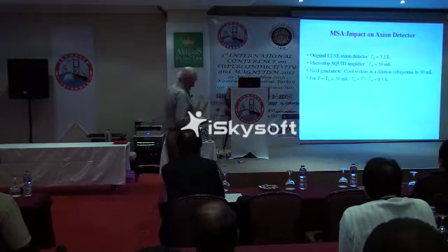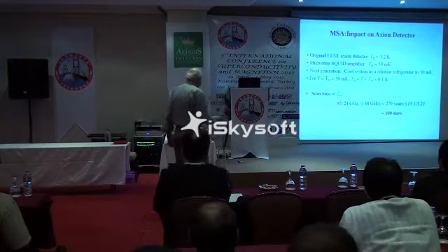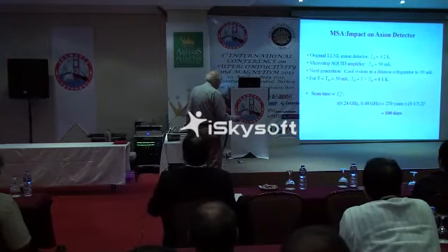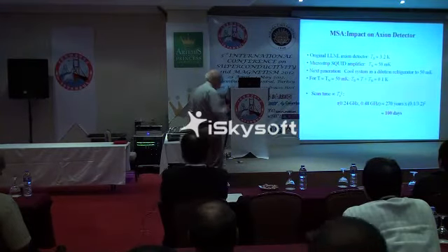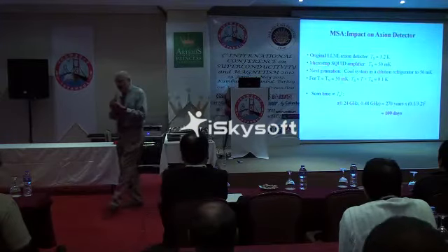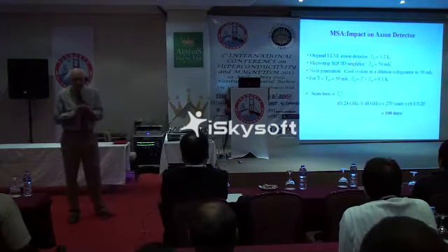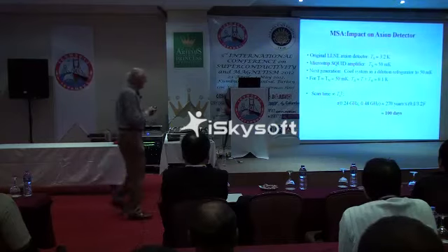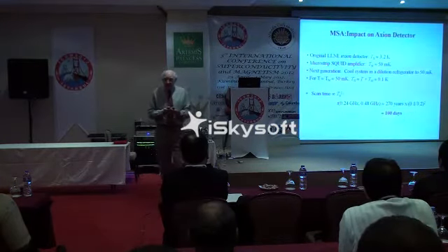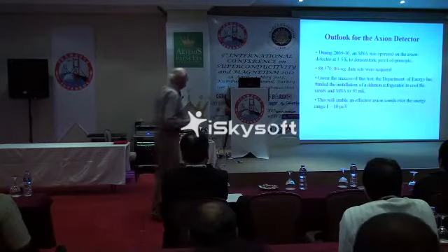And the impact on the scan time is dramatic. Since the scan time goes as the square of the system noise temperature, our 270 years is reduced to 100 days. So you can see, by introducing this nearly quantum noise limited squid amplifier, you can turn a project that was, for all purposes, dead in the water, to a project that is actually very viable.